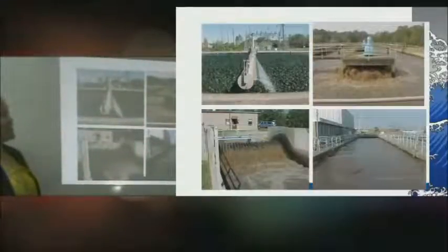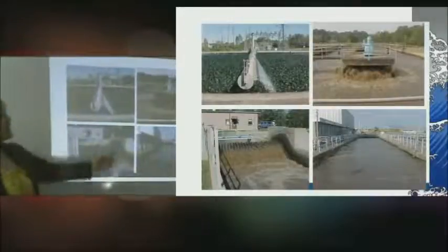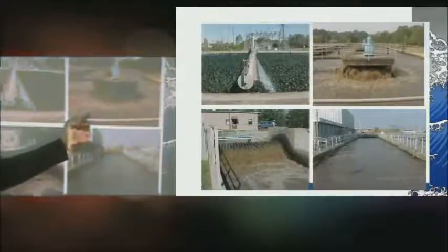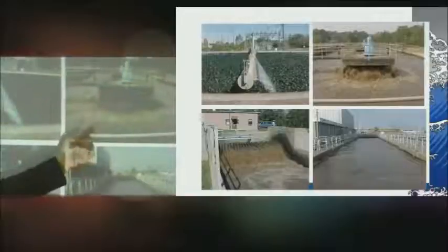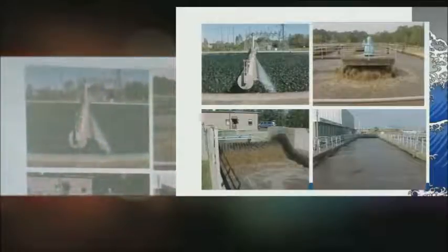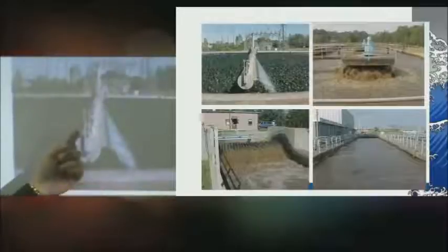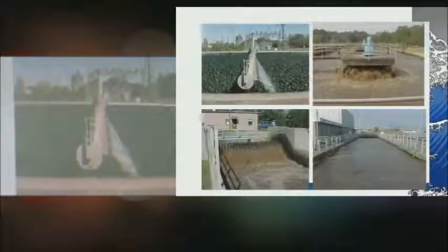Some of the biological treatments are shown in the figure. This is an example of an aeration process. So it's a biological treatment. It's aeration and it is exposed to the atmosphere. Therefore, what type of organism do we need here? Aerobic organisms. How about this one? This is what you call a trickling filter. It's actually a moving trickling filter.